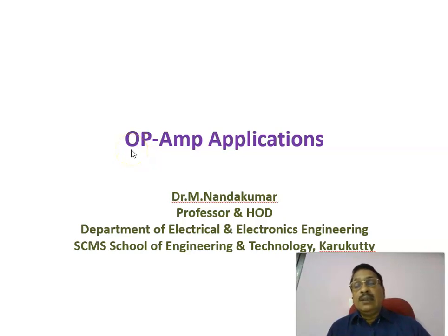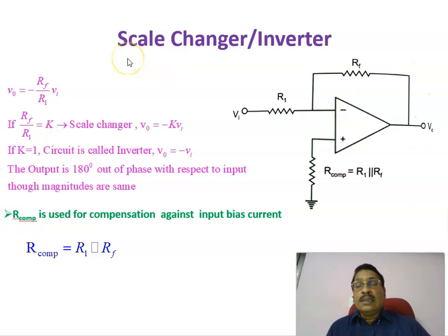In this presentation, I will be explaining the different applications of operational amplifiers. Let us consider the first application, the scale changer, which sometimes can also operate as an inverter. It is an op-amp circuit in which you are giving the input to the inverting terminal.